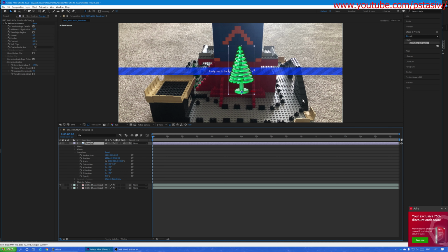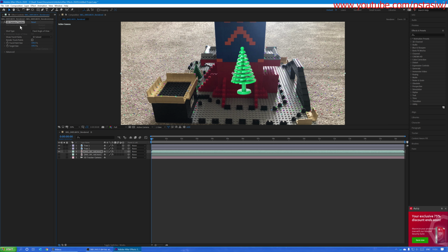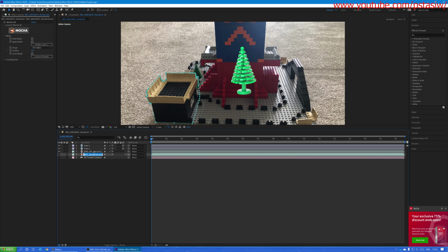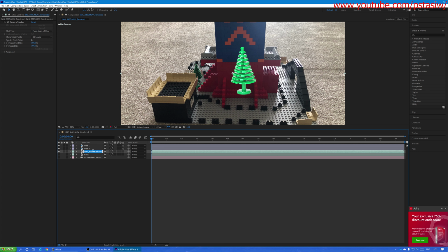And then we just wait until the analysis of the 3D scene is done. We're back, and the 3D camera tracker has analysed all the footage, and we've now got some points. To see the points, you go to the track which has the 3D camera effect on, and then select the effect 3D camera tracker, and then you get all these points here. To avoid confusion, I'm going to call this my mask from the previous video, and this the 3D camera footage, right?